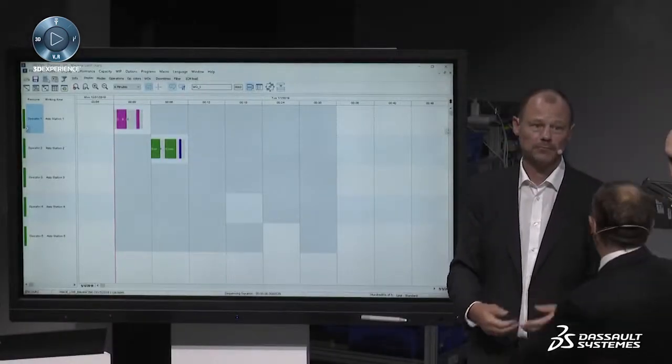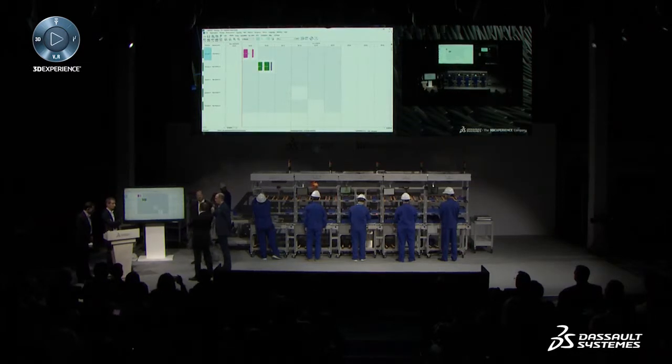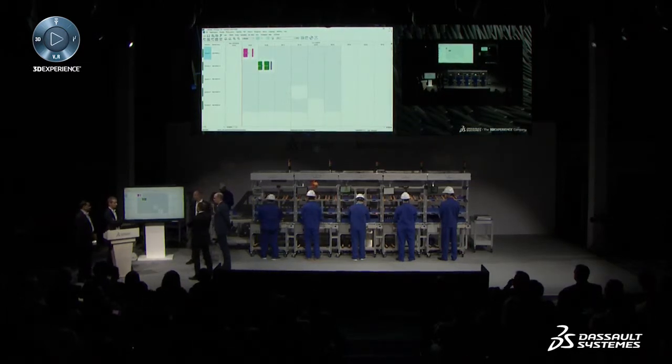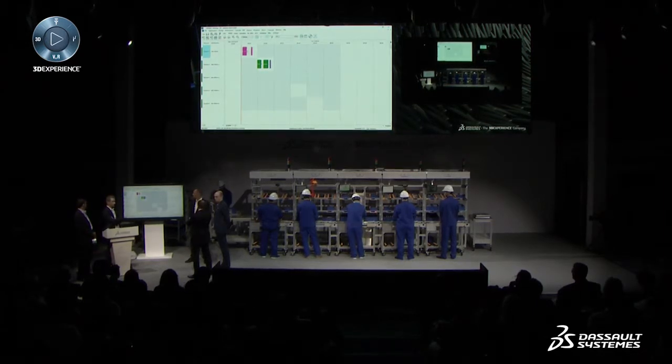Okay, so that's good and bad news. Let's say that you double the takt time, so we decrease our throughput basically, which is not good, but we still can produce, and we will use fewer operators on the line. Okay, so for me it looks good.